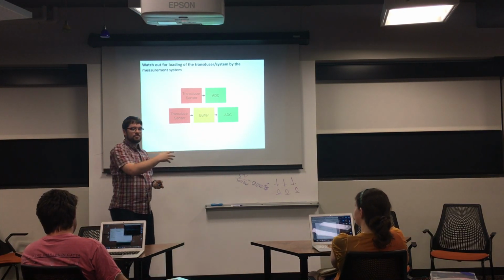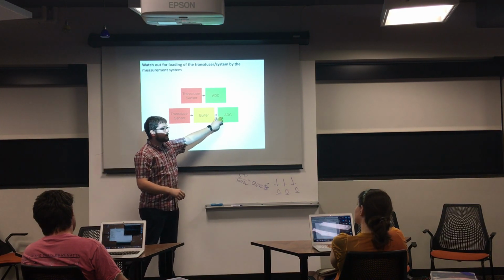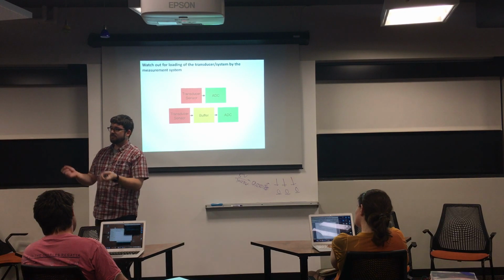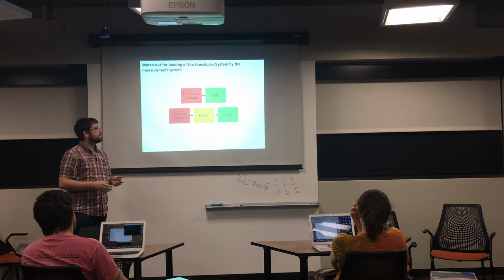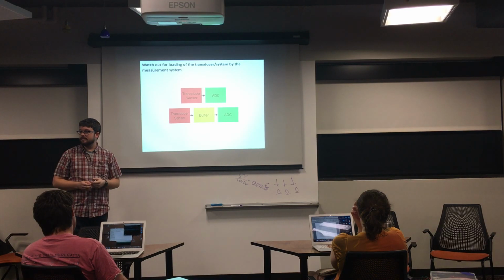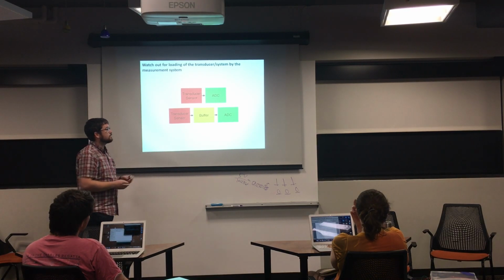But more often than not, we know the act of measuring your transducer or sensor can affect it. So you're flowing some amount of current into the analog to digital converter, it causes the voltage that the transducer is putting out to droop somewhat, and you get an inaccurate reading. And it's not necessarily always just a static offset. So it can really mess with you.